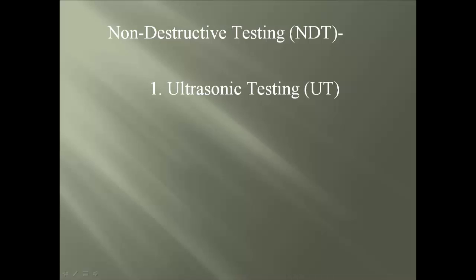First, we will cover the ultrasonic testing method, also known as UT, which uses a high-frequency sound wave, well above the human range of hearing. The transducer is attached to an electronic base unit which creates a sound wave that is transmitted through the test object until it encounters some reflector, which makes it bounce back to the transducer and ultimately displays on the visual screen for interpretation.